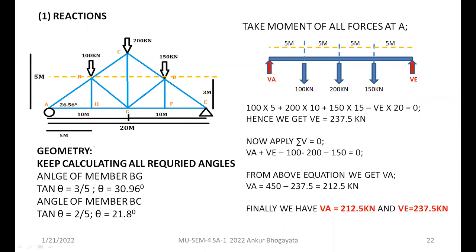You can simplify it because our first step is to find the reactions. So to find the reactions, you can go for this geometry and simplify the problem. You will be able to calculate the reactions within no time. This time we don't have any horizontal force, so a horizontal reaction at point E will not be there at all. So only 2 reactions are needed.